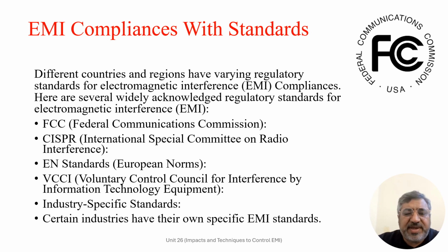sold in Japan. Industry-specific standards. Certain industries have their own specific EMI standards. For example, the automotive industry follows ISO 11452 for electromagnetic compatibility testing for vehicles, and the medical industry complies with IEC 60601 for medical electrical equipment.